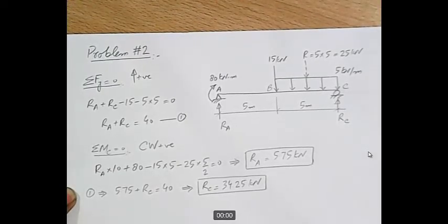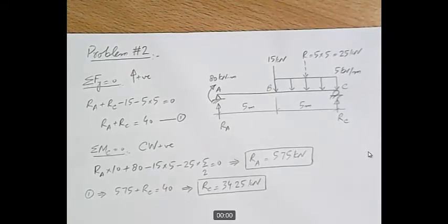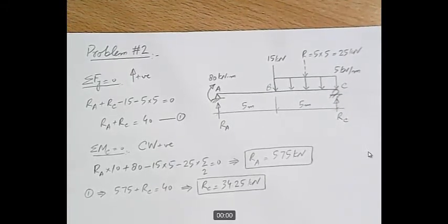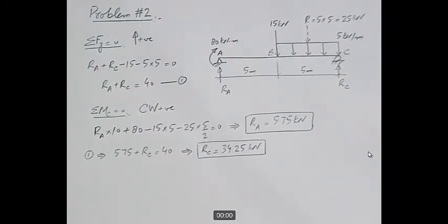Okay, now once again, in this direct method we don't have to go into that cumbersome procedure of writing down the equations for all the portions. Rather, once we have the reactions, we will directly jump to the plotting of SFD and BMD. So let's see how that can be done.